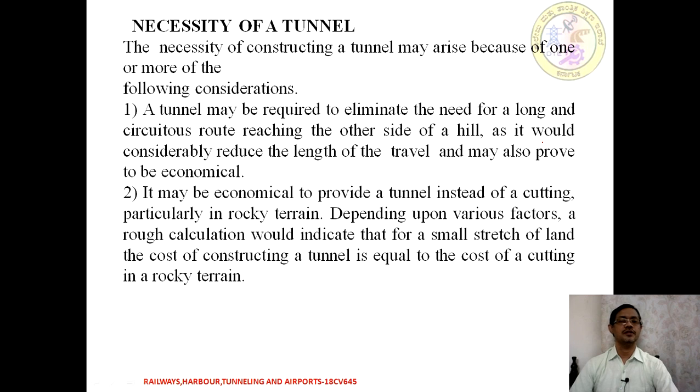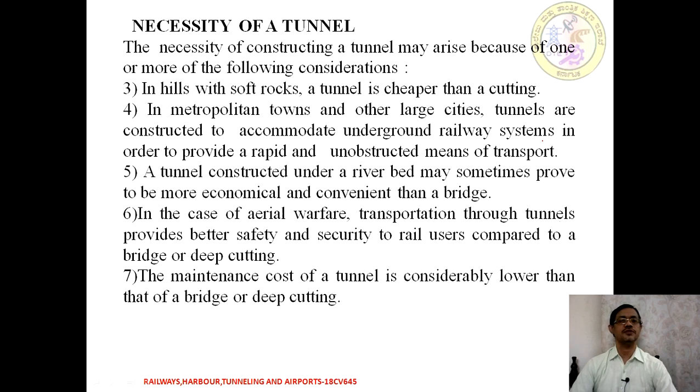To avoid a zigzag routing, especially in the case of a hill, tunnels are constructed. It may be economical, as it provides a tunnel instead of cutting through particularly rocky terrain, depending upon various factors. A rough calculation would indicate that the cost of a small stretch of tunnel is going to be equal to the cost of cutting through rocky terrain. That is what necessitates the construction of tunnels.